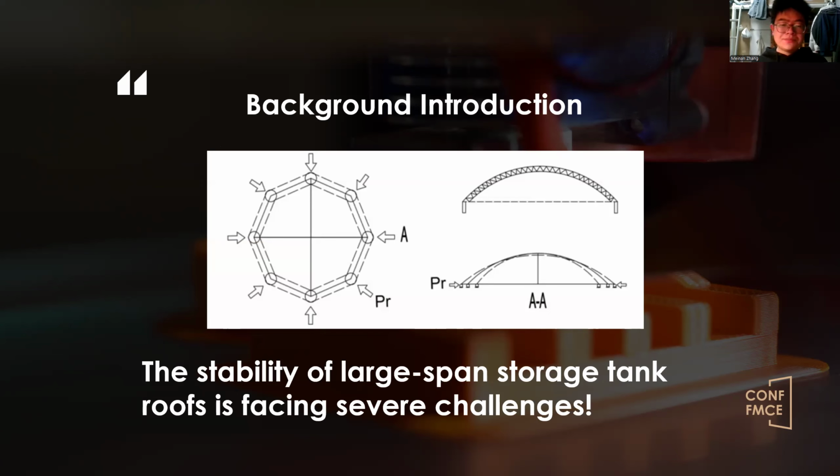As shown in the figure, prestressed cables can restrain the outward displacement of the reticulated shell through radial resultant force, reduce the thrust of the ring beam, thereby optimizing the internal force transmission mode of the structure and improving the ultimate bearing capacity of the structure.